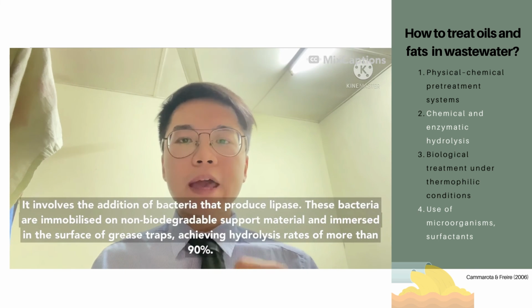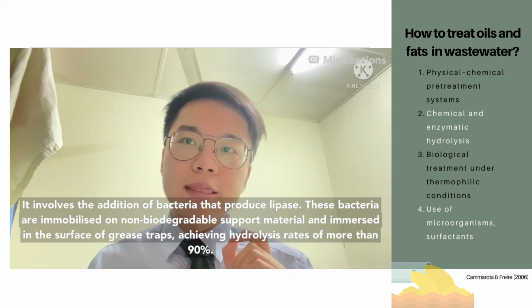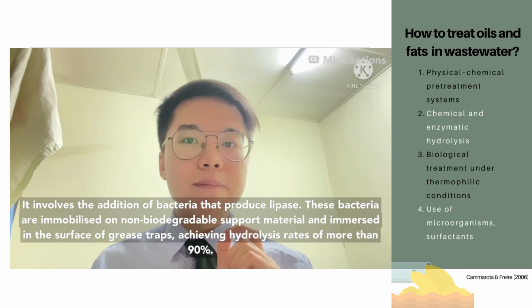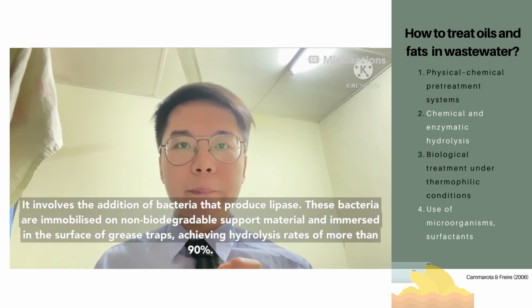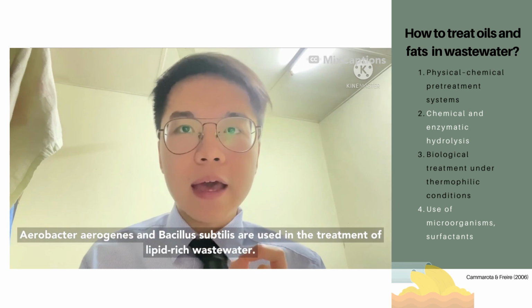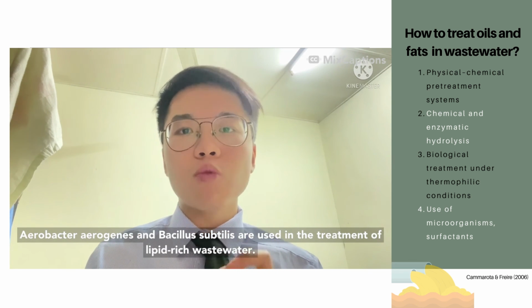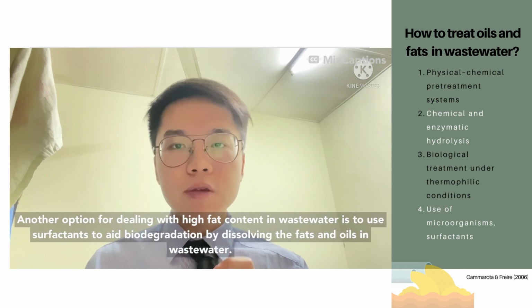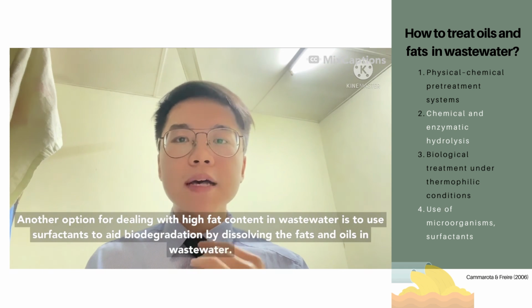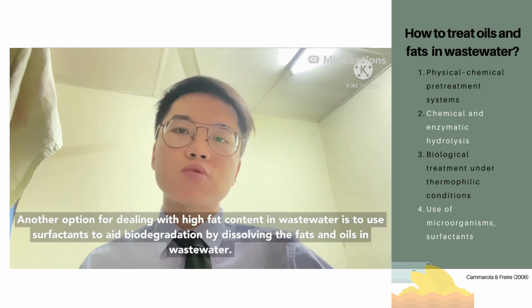Last but not least, they also use microorganisms to treat wastewater high in fats and oils. It involves the addition of bacteria that produce lipase. These bacteria are immobilized on non-biodegradable support material and immersed in the surface of the grease trap, achieving a hydrolysis rate of more than 90%. Aerobacter aerogenes and Bacillus subtilis are used in the treatment of lipid-rich wastewater. Another option for dealing with high fat content in the wastewater is to use surfactants to help the biodegradation by dissolving the fats and oils in the wastewater.